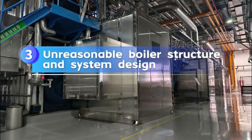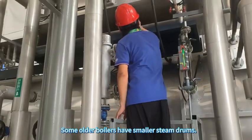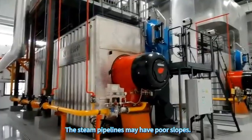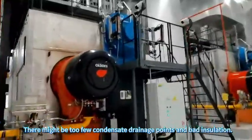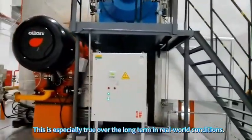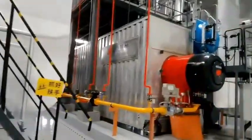Unreasonable boiler structure and system design. Some older boilers have smaller steam drums. They have simple steam water separation devices. The steam pipelines may have poor slopes. There might be too few condensate drainage points and bad insulation. Even if the original design was adequate, it is hard to keep high steam quality. This is especially true over the long term in real-world conditions.